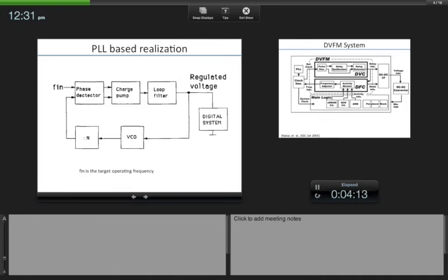So then you can just measure the frequency of the ring oscillator. Either you could measure the delay directly of the delay chain, or you can measure the frequency. We'll see how you can measure the delay of the inverter chain. But measuring the frequency is again pretty straightforward. So here what you do is, for example, we know that this has to be part of a feedback loop, right? So you want to achieve a certain target frequency.